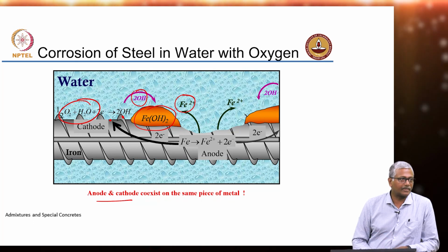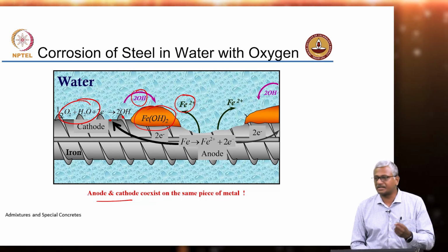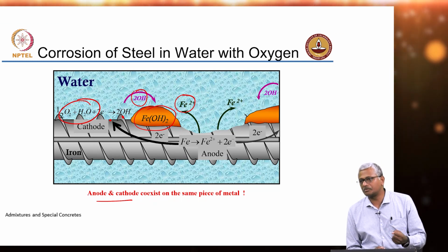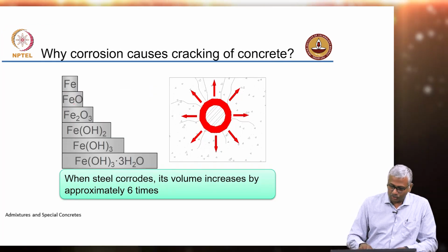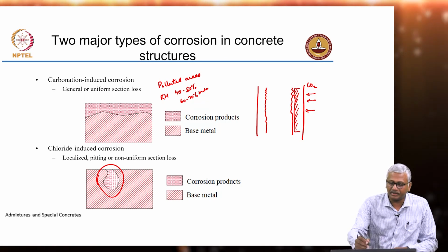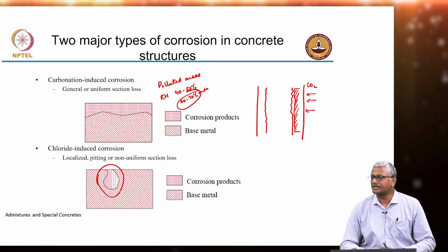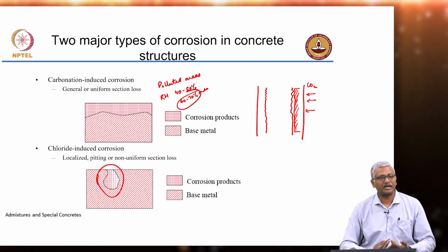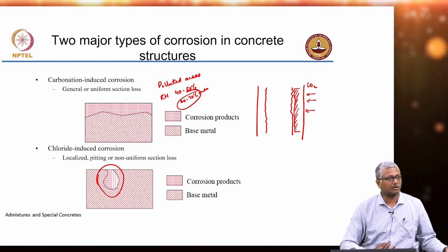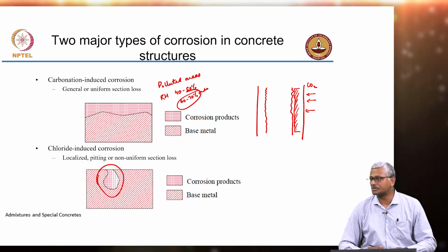And if your concrete is impermeable, you will further restrict the possibility of corrosion because oxygen and moisture are not available. Similarly, if you are in zones where carbon dioxide penetration is high, but there is not sufficient moisture available to cause the corrosion, you may get CO2 penetration deep into the concrete, but perhaps there may not be much chance of corrosion.